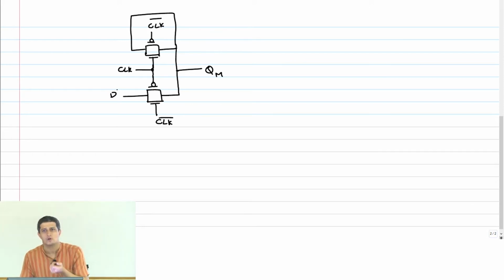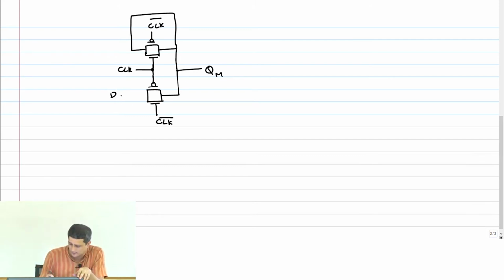Here, when I try to characterize, I need to know where this flop has been placed. Without that, I cannot tell you, and therefore I cannot design a standard cell element like this. Some special places you are free to go and place this circuit as it is and you get it to work. But in order to characterize it, I need to drive it through inverters, right? So that I can tell you exactly what the delays are.